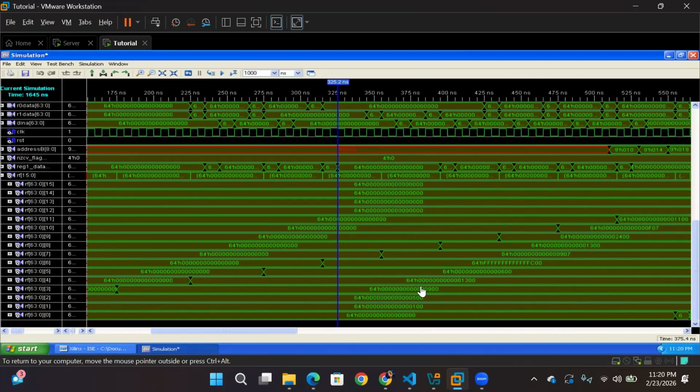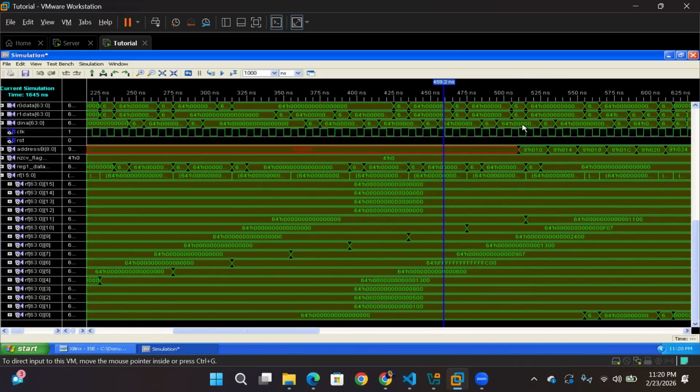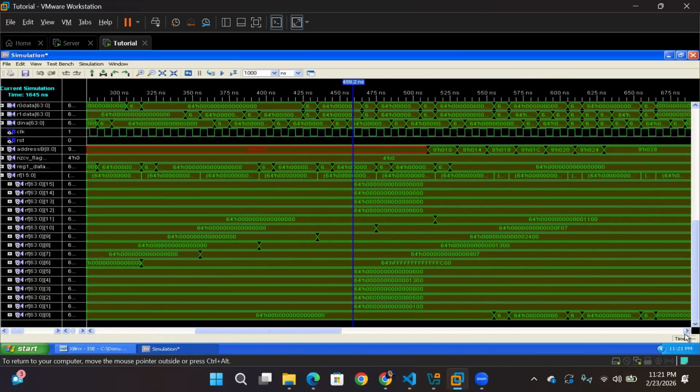The fifth is an R-type instruction, wherein we are adding R1 and R2's value into R5. And based on that, it's correctly tallying for R5 in the subsequent clock cycle. And then comes a sub instruction, R6, R1, R2, and yes, the data is also being loaded. In a similar manner, there are one or two more R-type instructions with the same logic, and then comes move R8, R4, wherein R4's contents are being exactly moved to R8's register, and that has also been clearly verified by the cursor, as you can see in the video.